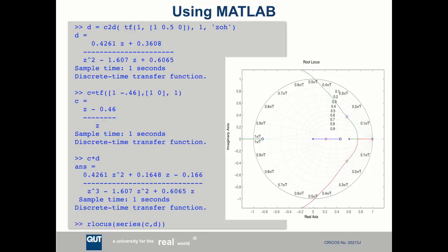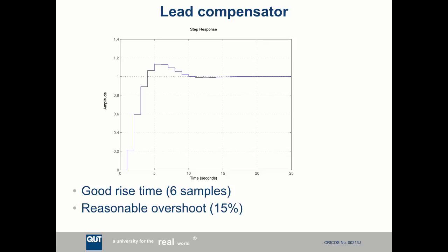So, they've got a nice damping ratio, they've got a nice natural frequency. Pretty simple bit of control design. Yep. And that's the step response. So it seems to settle in about 6 steps, 15% overshoot, all pretty nice.